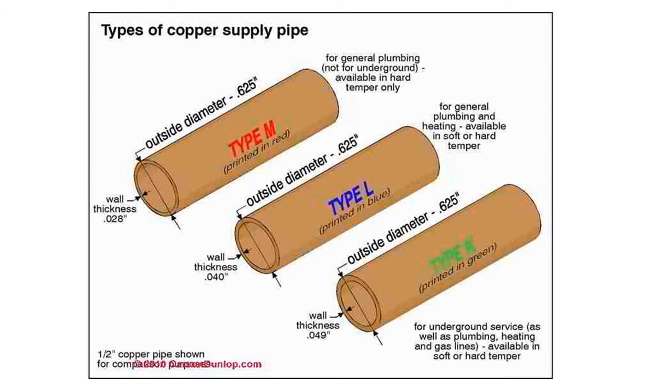Hard-drawn copper tubing is marked to indicate its wall thickness and usage with the following letter designations: K, L, M, and ACR. Type K has the thickest wall section of the three types of pipe and is commonly used in underground burial with a suitable corrosion protection as required by code. It has green-colored printing. Type L has a thinner wall pipe section and is used in residential and commercial water supply and pressure applications. It has blue color printing.